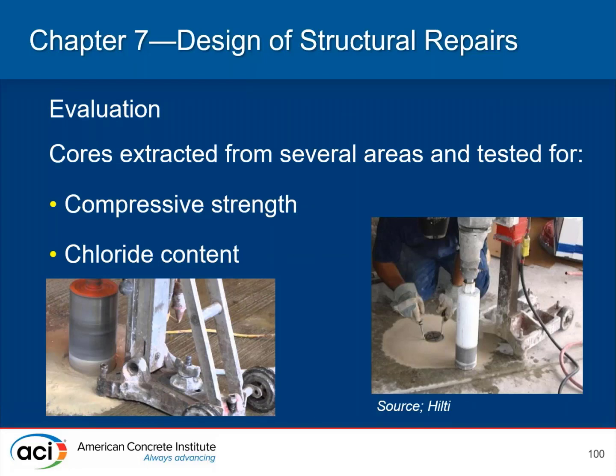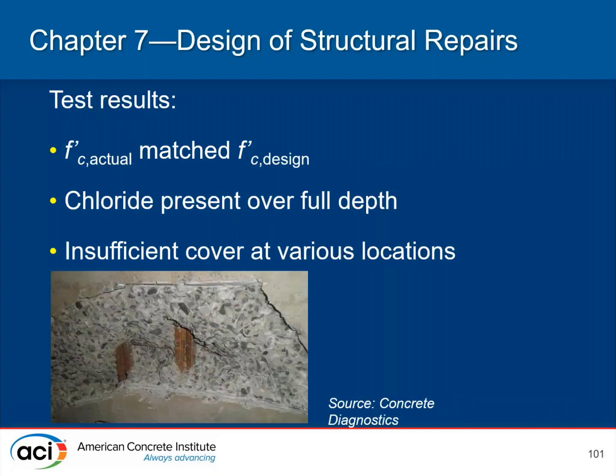In the evaluation, cores were extracted from several areas and tested for compressive strength and chloride content. Chloride content is of importance when you are evaluating the corrosion potential of reinforcing steel in concrete. There are a variety of other techniques that can be used as well if deemed necessary by the LDP with respect to evaluating deterioration and corrosion characteristics.